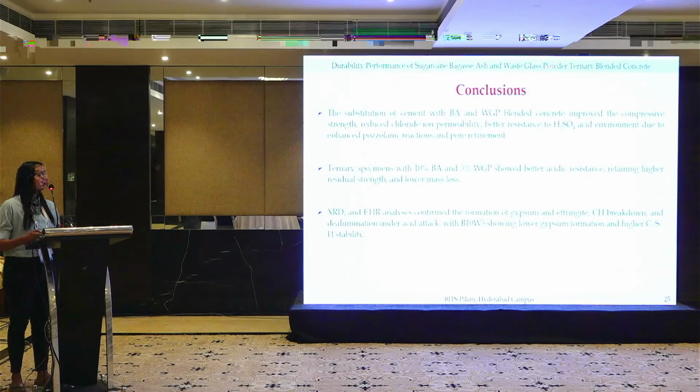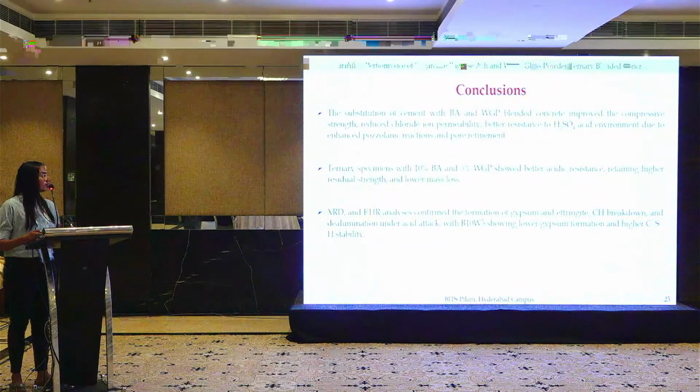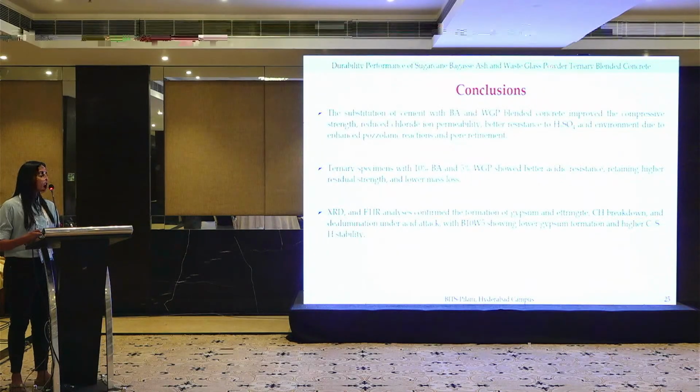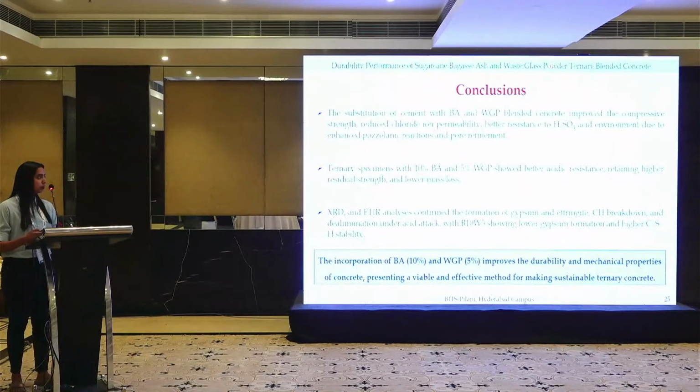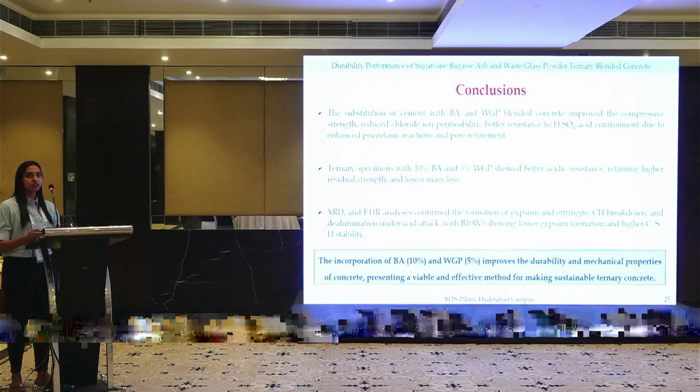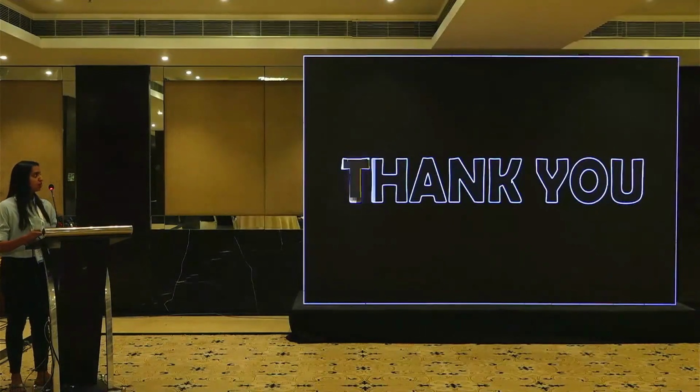So the XRD as well as FTIR analysis also confirm the formation of gypsum as well as ettringite, CH breakdown as well as dealumination under acid attack in the control concrete. Waste glass powder improves the durability and is an effective method for making sustainable ternary blended concrete. Thank you.